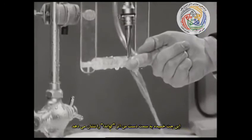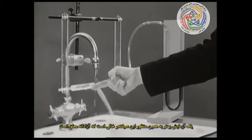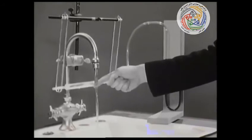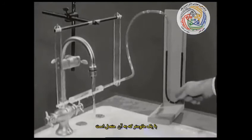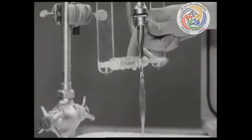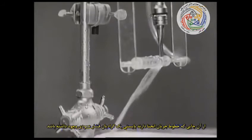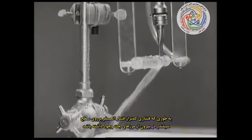This bending of the jet toward my finger is the Coanda effect. A better experimental setup is this freely suspended hollow cylinder with a small static pressure hole connected to a manometer. Since the streamlines are curved, there must be a normal pressure gradient, with the pressure at the cylinder surface less than the atmospheric pressure at the outside boundary of the jet.